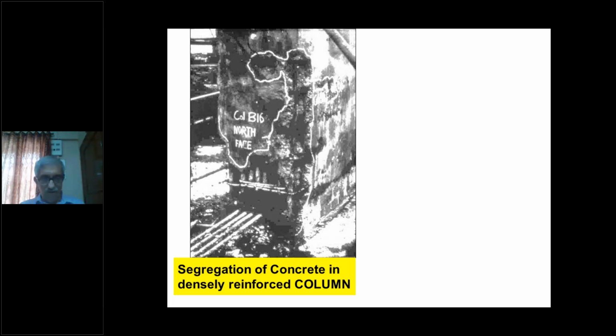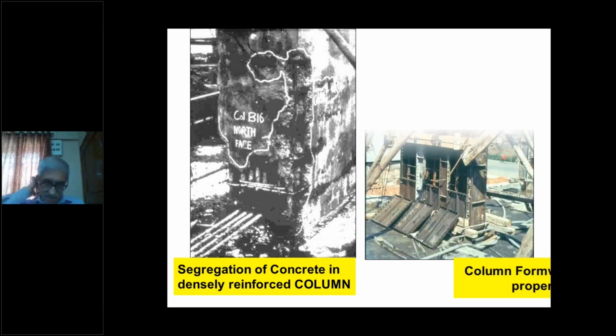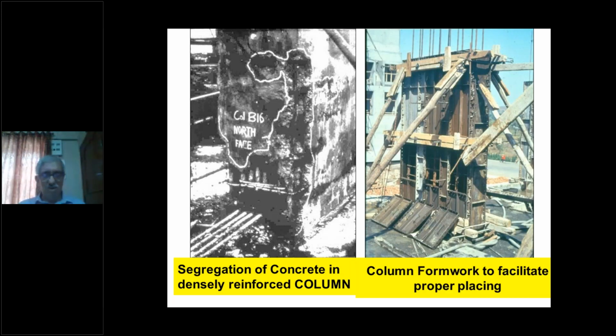So segregation of concrete in densely reinforced columns is observed when concrete is dropped from the top. So one has to do concrete in a careful manner.